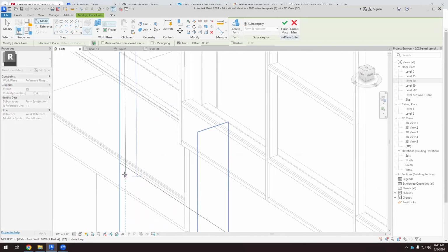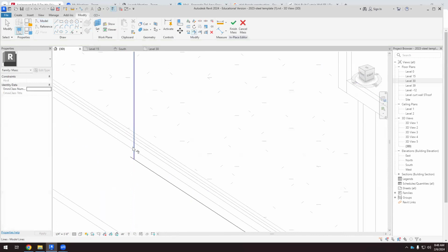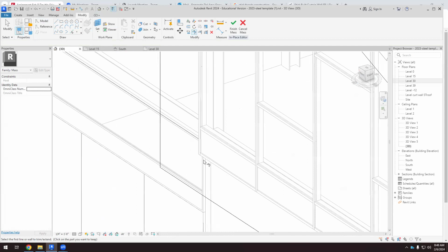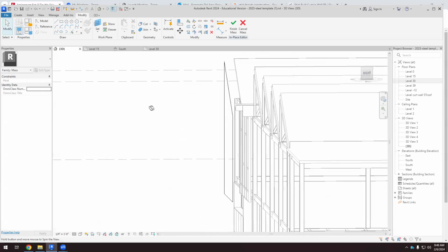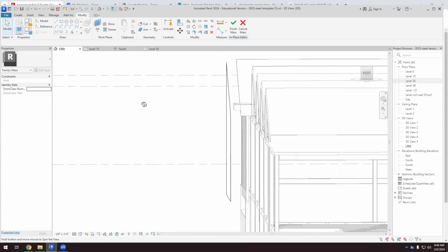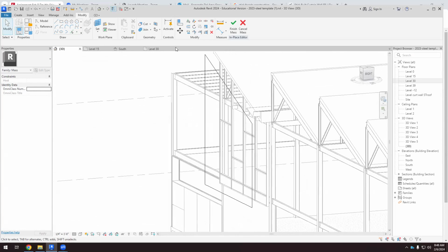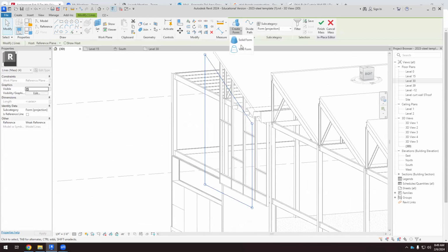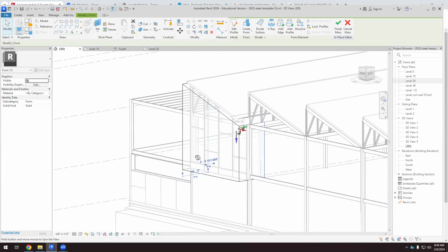and this one. If there is a gap here, I can trim. There you go. Okay, so you see that I have created this shape. It's in the right plane, in the double skin reference plane. And now I have to select the chain of wall lines. So I have to select everything and create a solid form. So if I create a solid form, I have something solid,